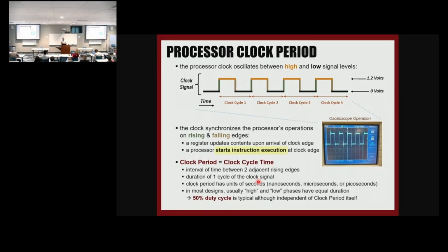If you have a base clock that's synchronizing everything, and let's say its duty cycle isn't quite 50%, would that matter? If it's the authoritative synchronizing clock, would you even be able to notice if you have ended up with like a 48% duty cycle? It's a very good question. It matters if you, for example, are doing something at the negative edge of the clock too.